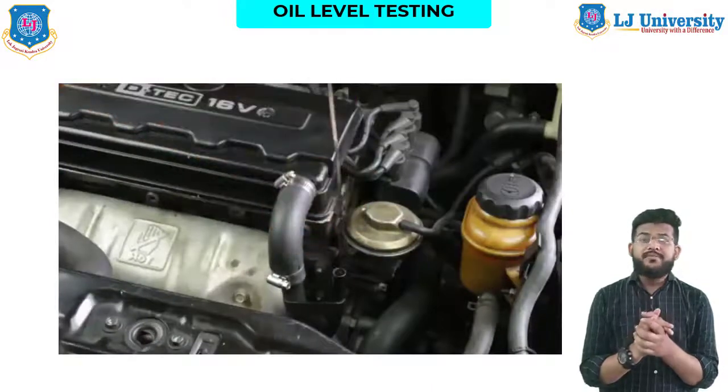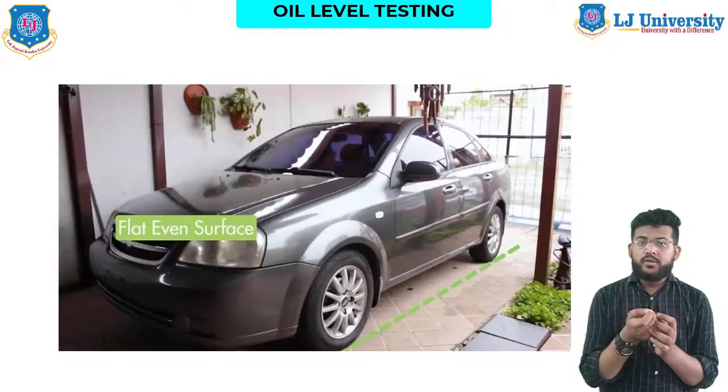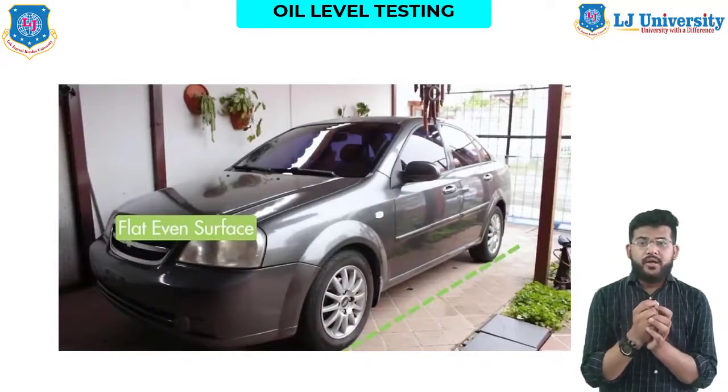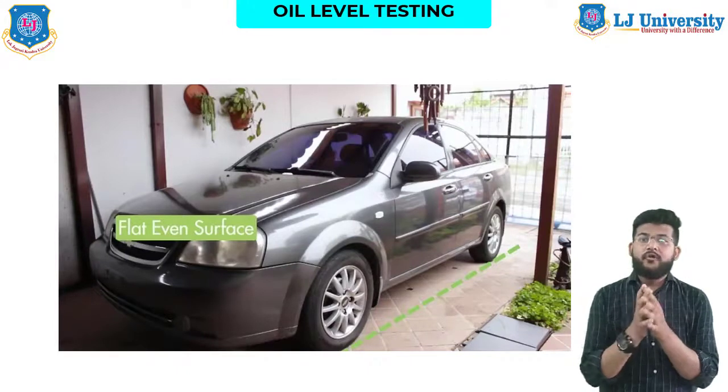First, pull out the dipstick and wipe it off with a clean cloth. Be sure that the engine is cold and not running. If it has been running, keep it off for 10 minutes before you check the oil level.